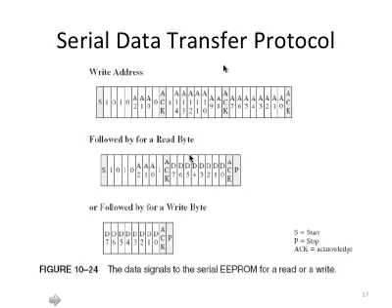And this ACK will be the response from the EEPROM chip. After that, what follows is the real address to the content stored in that chip. So don't confuse these A2, A1, A0 with these A0 through A14, which are the real address to access content within that EEPROM chip.